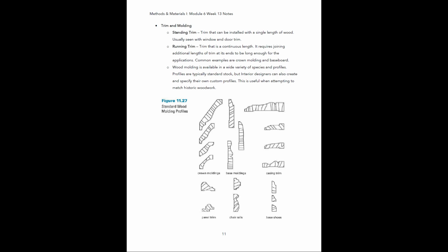So if you were to go to a millwork manufacturer and say, hey, I want you to match this woodwork, typically within their standard catalog of profiles, they would not have a perfect match to what you need to one-to-one match it. So what you can do is you could actually give them a sample of the old woodwork from that building. Maybe you just pop a piece off and you take it into the millwork manufacturer and they look at it and then they can actually custom match that shape, okay?